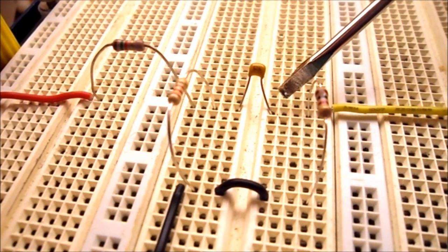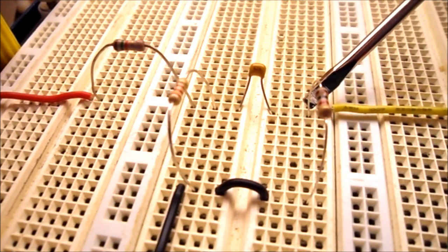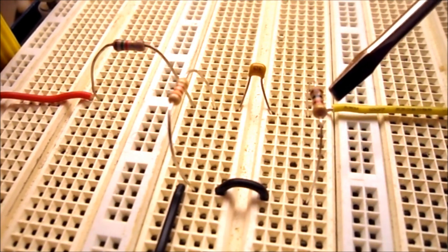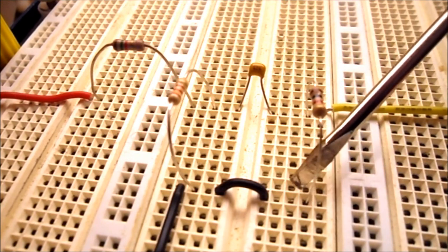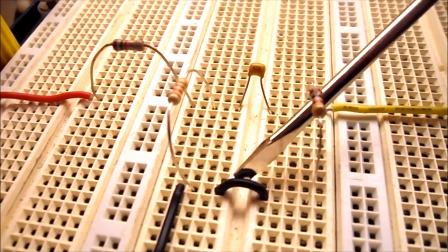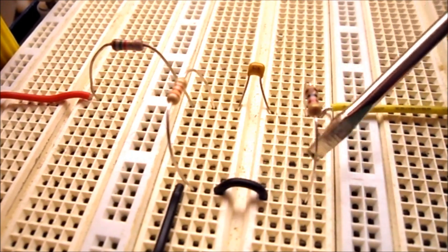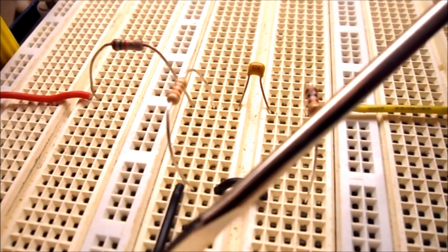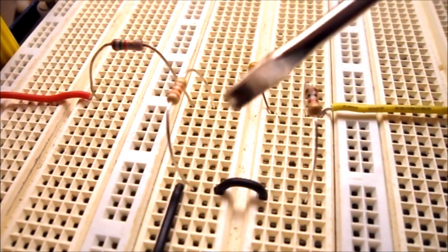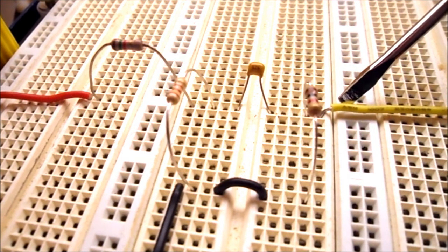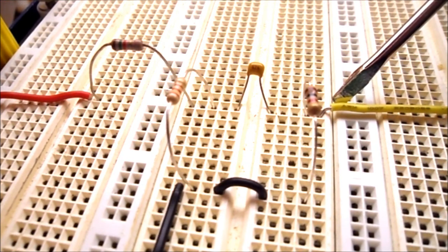Now that's going to join in this bus with our load, which is 1K ohms, and it comes back, and I have to have a little black jumper wire to continue the bus line over to the common that goes back to the common of the function generator. This yellow line is going to go to channel 2 of my oscilloscope because that's V load, or the output voltage.